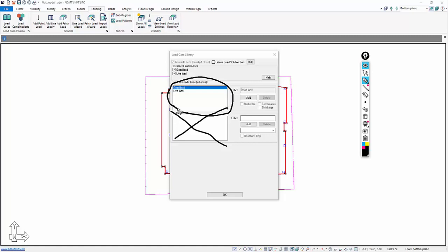Even if you're modeling lateral load reactions like overturning moments or base shears, those load cases should be defined as load cases in the general loads gravity/lateral. This lateral really should be intended for lateral reactions on a foundation.